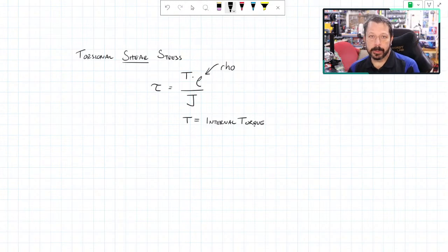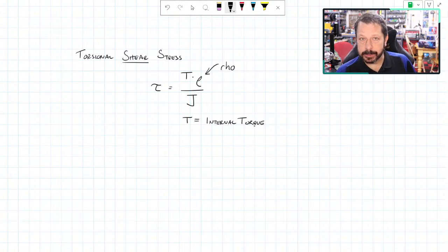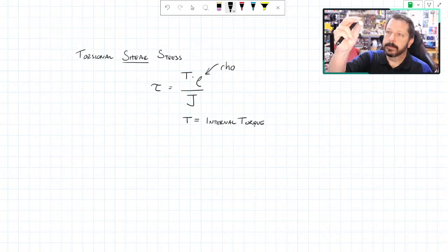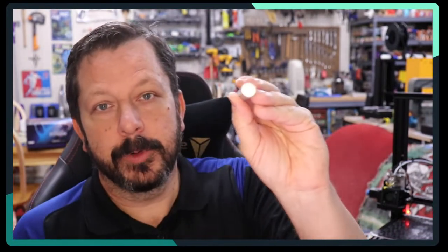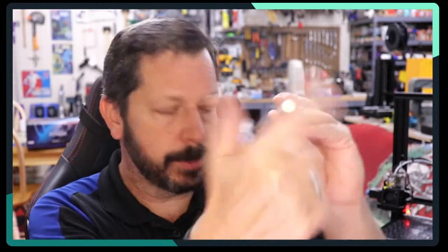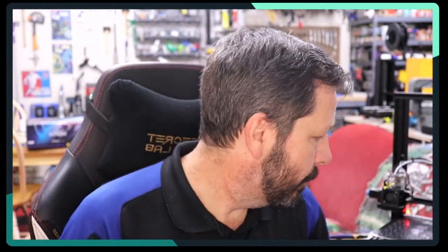This is the torque that is trying to twist whatever kind of shaft. We're only going to deal with round shafts. So they can be tubes, hollow on the inside, but they're round. We're not talking about something like this, where the shaft is a, what is that, a hexagon? Yeah, hexagon. So no, none of that. You could do that, but it is going to be a different, it's the same type of equation, but J, when we get to that, that'll be different. So only round cross sections, not hexagons or stuff like that. Actually, this is tapered, so this would be a little bit different.